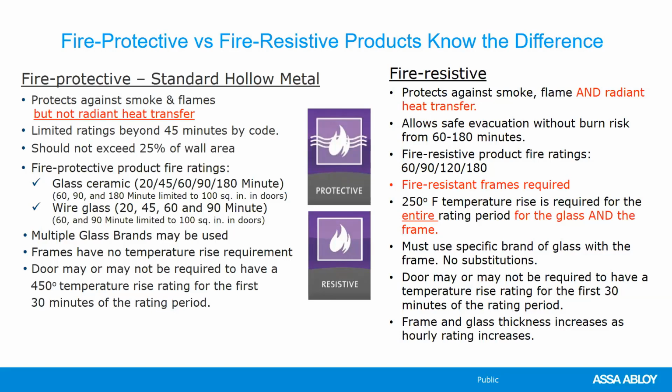The other difference is that fire resistive product is primarily used for ratings of 1 hour and greater. Fire protective is only allowed for ratings up to 45 minutes by code. Again, this is by code, and that is something that we'll get into in a little bit here.